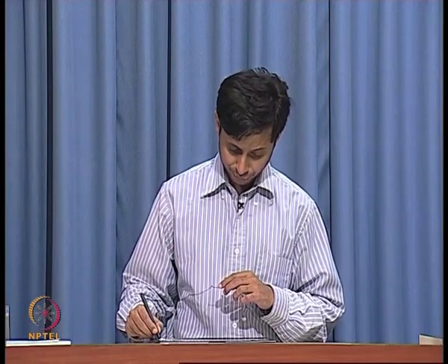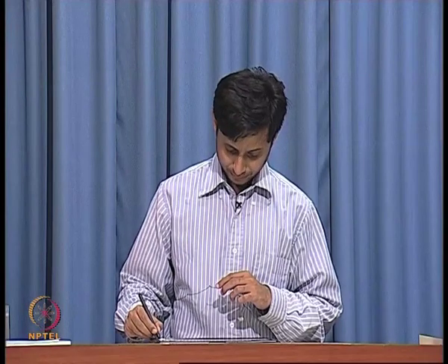piece of wire and developed a model for the wire. Now, we noticed that the wire had a little bit of inductance per unit length, a little bit of capacitance per unit length, some resistance per unit length, probably hopefully not some conductance per unit length, and we cascaded these small units and made the complete wire.